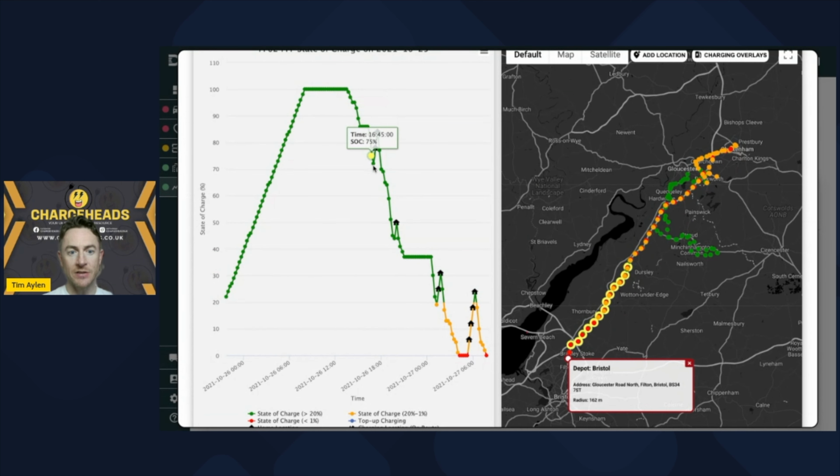And then it comes back to site and there's an opportunity to charge. It's there for half an hour, so it charges on the 22 kilowatt charger up to 84%, and then off it goes again. It draws down the battery, there's a 15-minute opportunity to charge, then off it goes again. Then obviously someone stopped at a job or a long dinner, and then off it goes again, charging. Then as it gets into yellow-orange here, that's under 20% state of charge, a bit of a warning. And then red is dead.